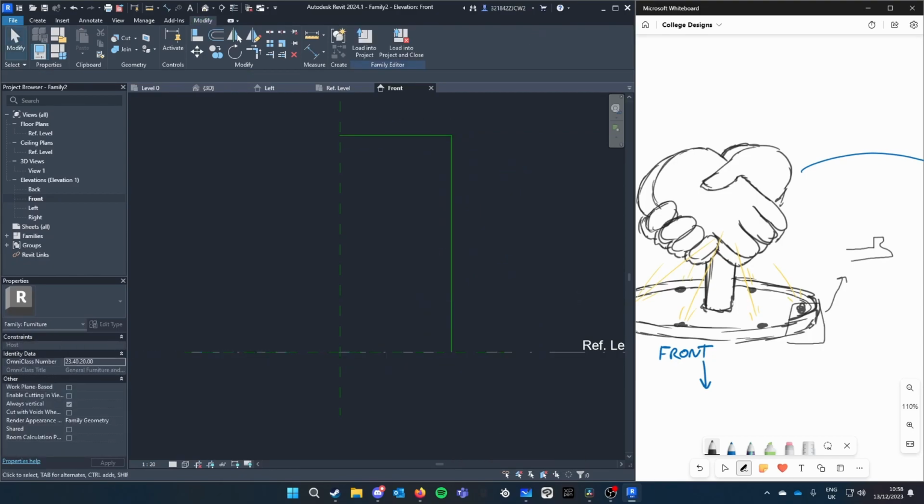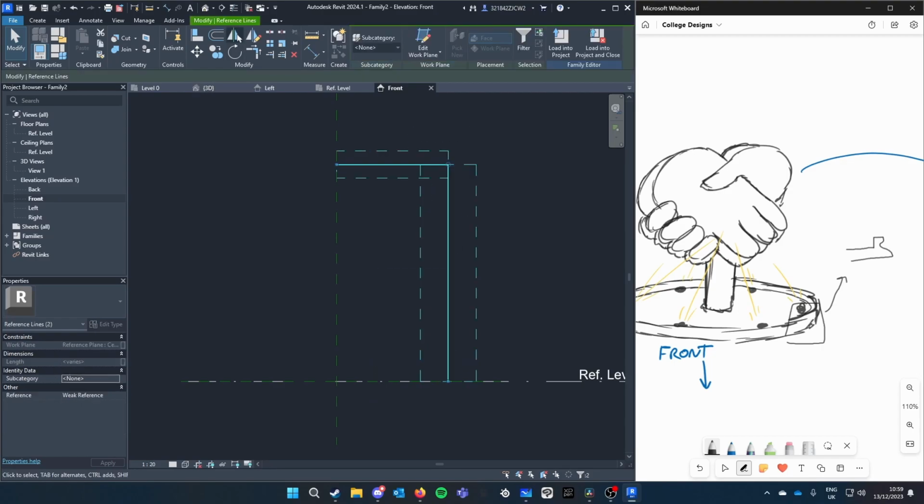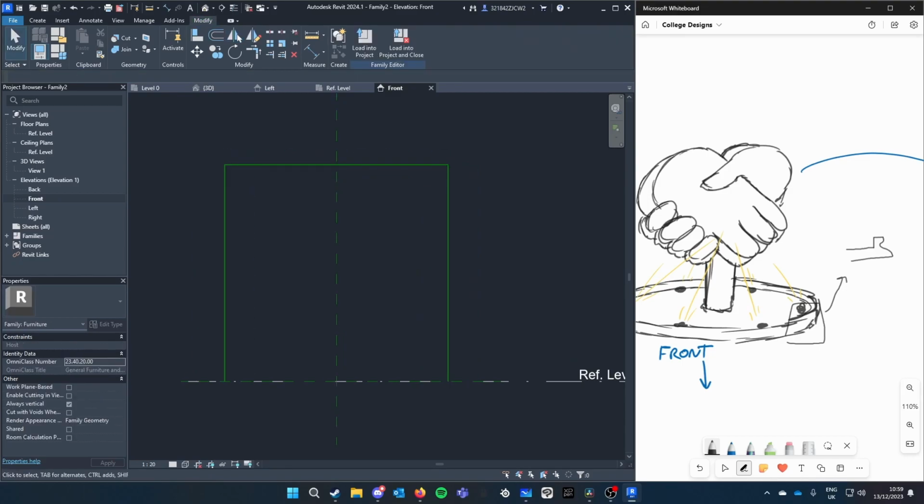And I want to mirror this on the side, so I'm just going to select them both. Quick tip, if you go from the bottom right going up, it selects whatever you go across. If you go from the top left down, only what you've fully highlighted will be selected. So I'm just going to go this way, select them both. And you can select the mirror axis tool here, or just double press M on your keyboard. And select the object to mirror it across. So I'm going to mirror it across this axis. So, boom. We got our square now that we're going to be building in.